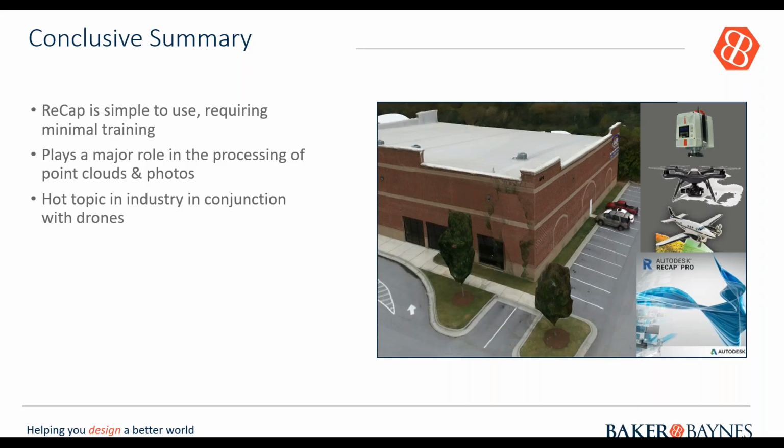Okay, so we're just going to conclude on that very quickly. As you saw, it's easy as literally 1, 2, 3. You take the software, or you take your drone, your machine, and take your photos, making sure they're geolocated. Import them or copy them to your PC. Thereafter, select all the photos that you need, and from there, it will process them in the cloud.